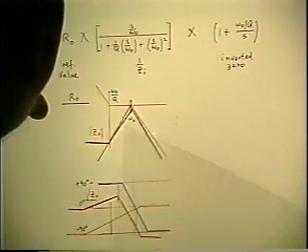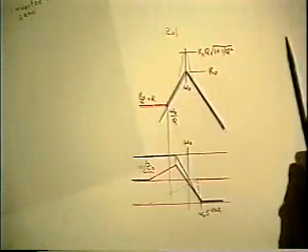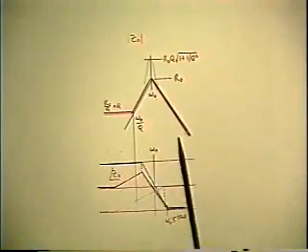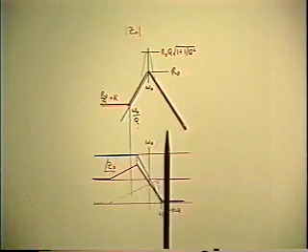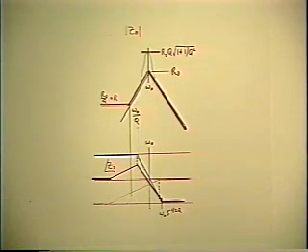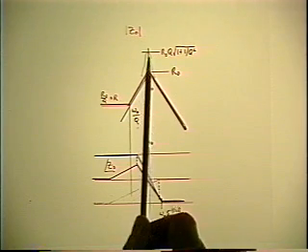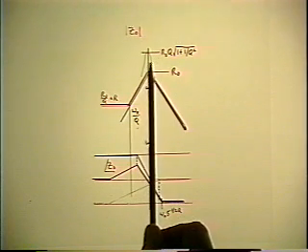And as before, I can restore the high Q peak again, surrounding the peak of the output impedance, and you get the familiar result that the output impedance is a parallel resonance that has a high peak value.